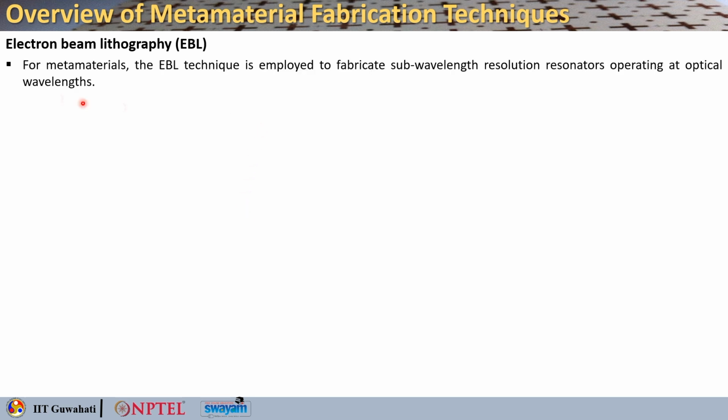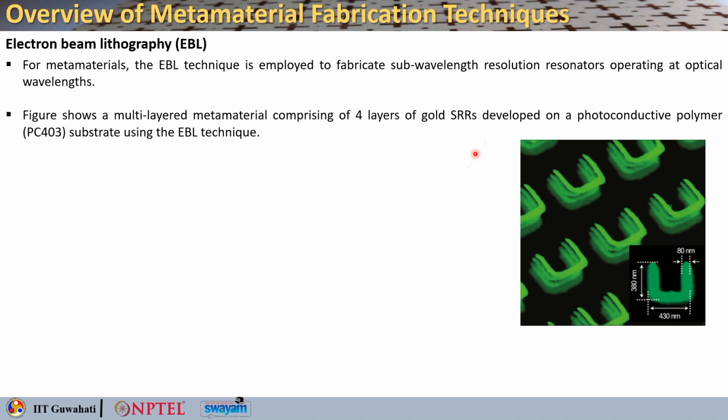For metamaterials, the EBL technique is employed to fabricate sub-wavelength resolution resonators operating at optical wavelengths. So, this is mostly useful for optical metamaterial fabrication. The figure here shows a multi-layered metamaterial comprising 4 layers of gold split ring resonators developed on a photoconductive polymer substrate PC403 using the EBL technique.